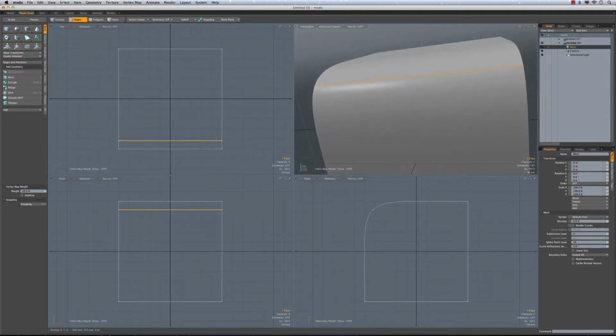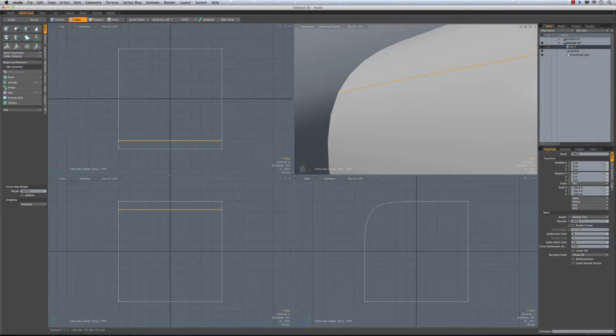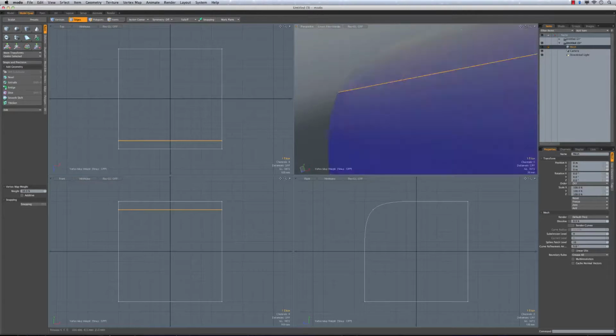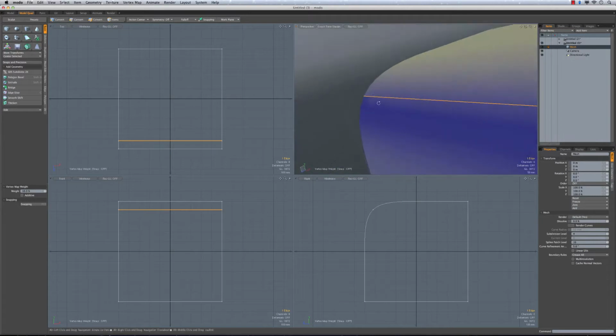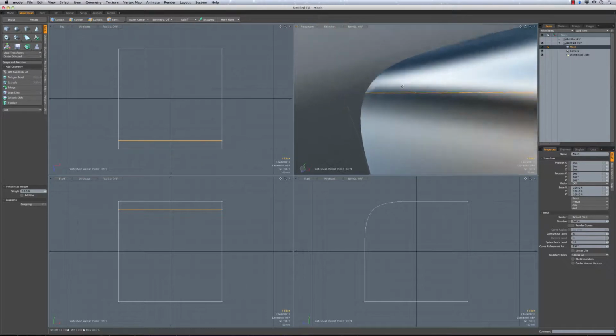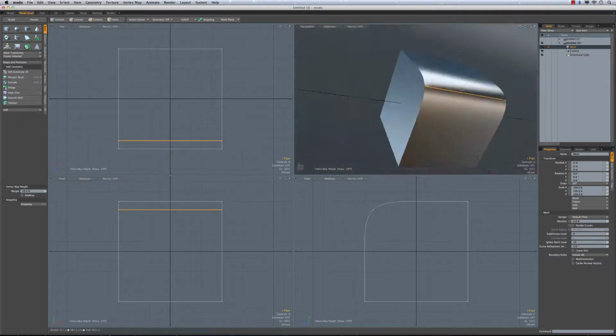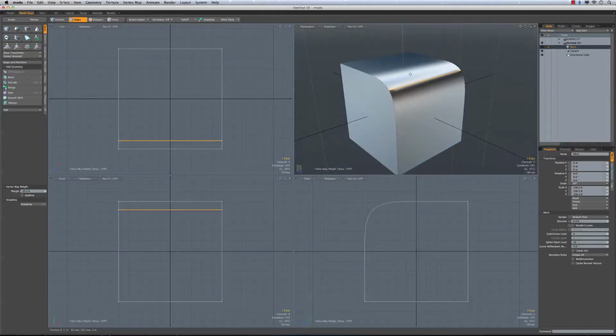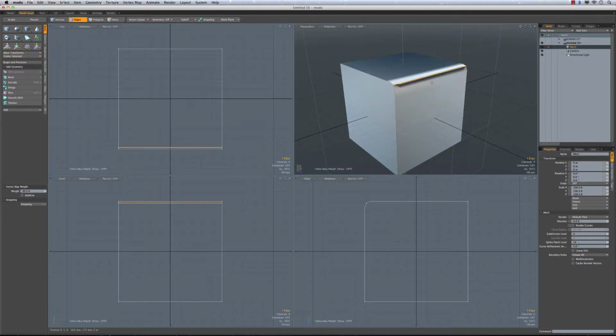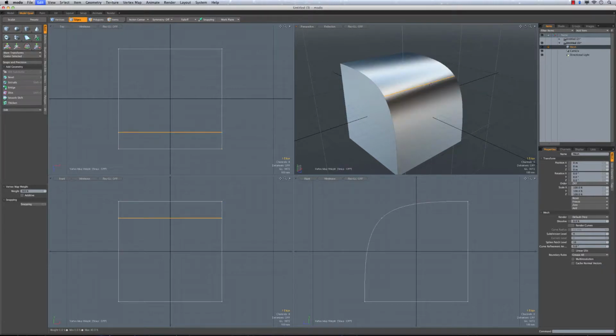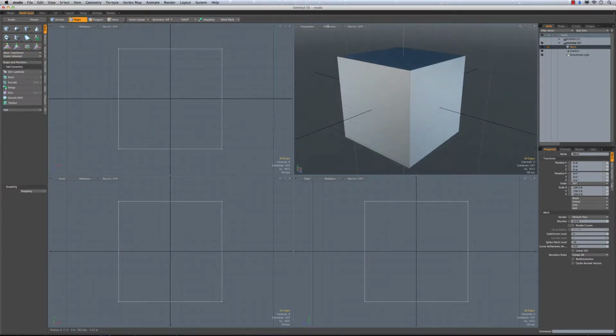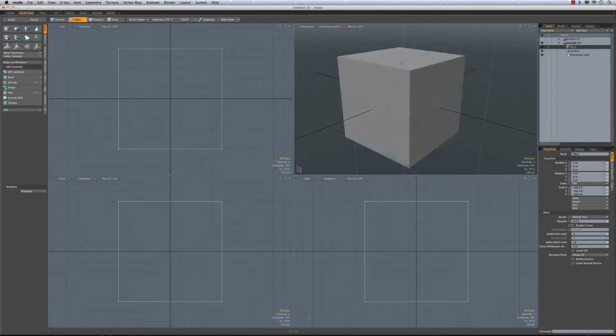And even this one here at 10%, if we look here and get something like, say, the Gooch Tone shader, where I can see a little bit more of my instance angle, you can see there is definitely a bit of a flex there at that corner and some inflection in the surface. The reflection shader should show it as well. So you can see that's really not what we're going for. So there are a couple of things that need to happen in order to get some rounding and some otherwise sharp bits here. So let's go back to everything being at 100%, and I'm going to go back to my advanced OpenGL.